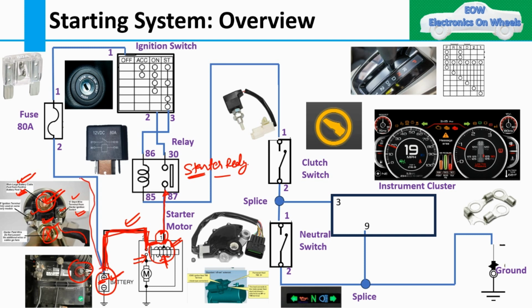Then we went to this particular circuit, and this circuit is going to the fuse. This is a maxi fuse of 80 amps, and here we are just taking this fuse from here to here for this ignition switch. Definitely there would be some more fuses. A direct fuse of 80 ampere is not required for the ignition switch, but I just showed here that there would be power distribution from the battery to the ignition switch through some fuses. This would be the maxi fuse. If you see the fuse, it will look like this, and this is the filament of the fuse. So now you come to know the purpose of this fuse.